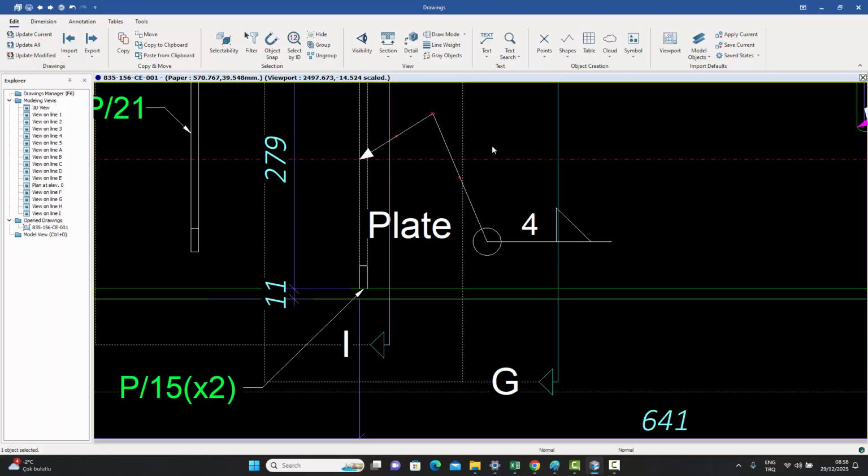And once that is done, each leg now has a middle point. So if you select it again, you can now select this particular point and break that into multiple legs as well. So you can basically break the welding symbol into multiple legs from that point onwards.